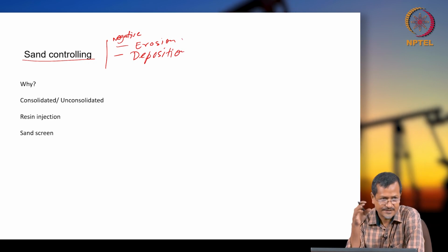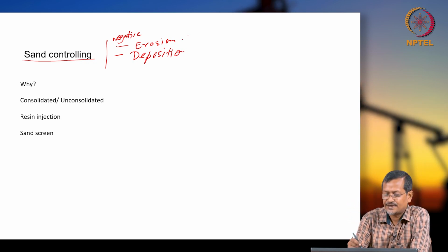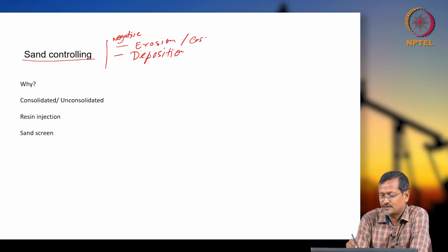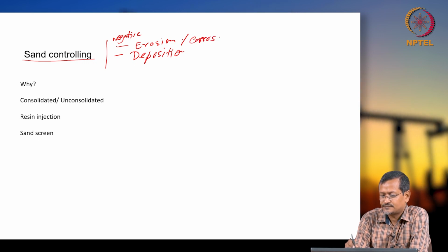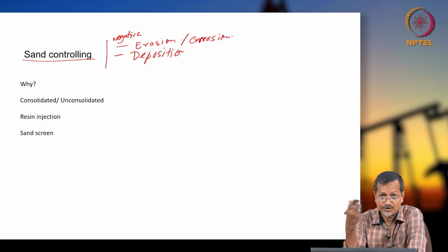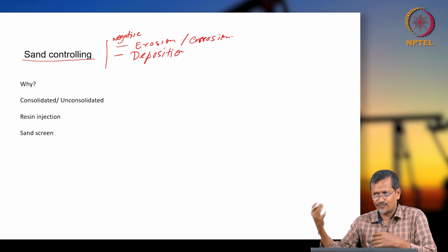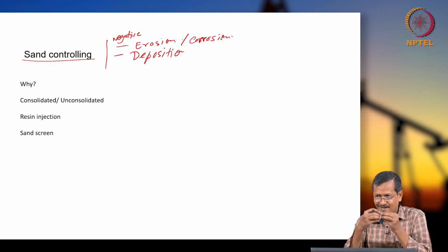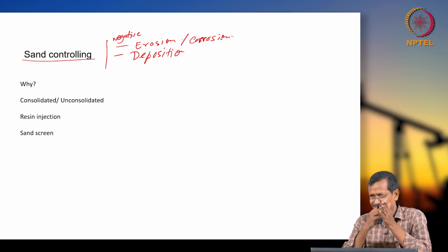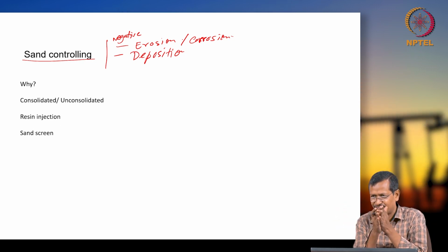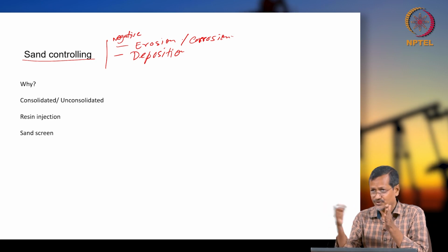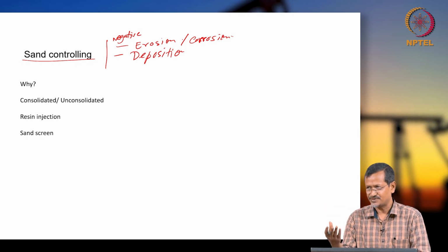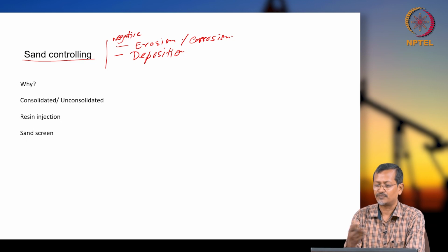It will be eroding the surfaces, and if corrosive fluid is there, then corrosion also will be assisted. Corrosive fluid will get a new surface every time, as the sand removes the salts, again giving a fresh surface to the corrosive fluid. So it will be increasing the corrosion rate or erosion rate, or together you can say.